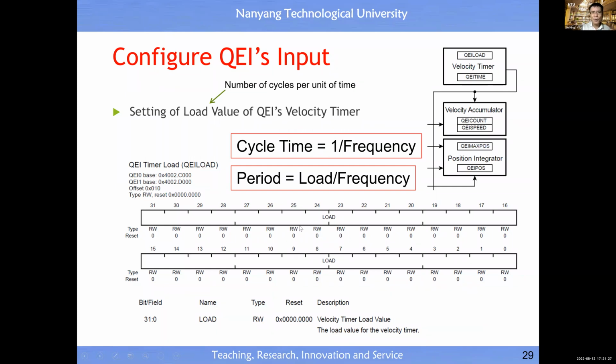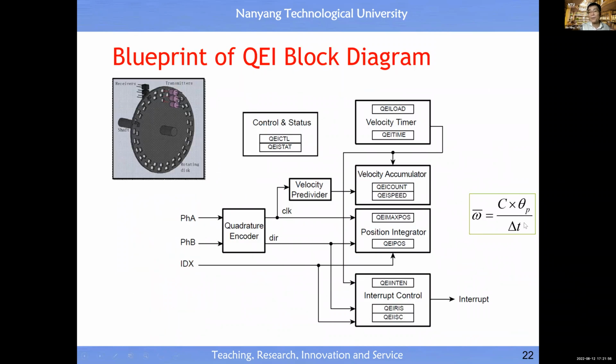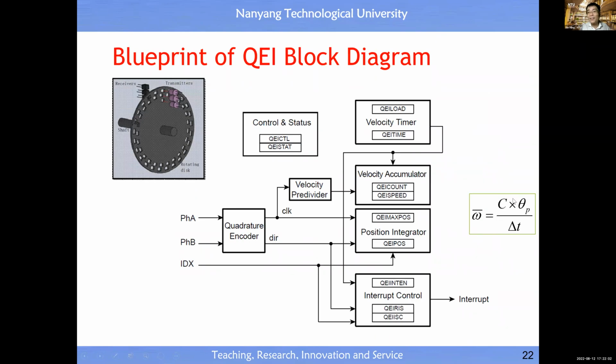Since we have 2 interfaces, we can take in 2 sensors. So you actually have 2 units of this digital sensor interface, QEI 0 and QEI 1. You can have a different rho value, so your observation time could be different. This is the first thing to do, which is to set delta T. The equation is here, actually to determine delta T. Very simple.